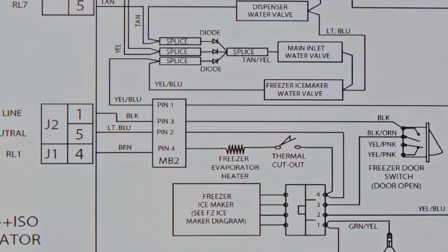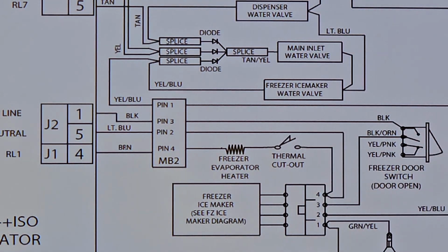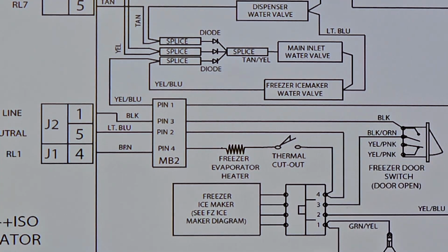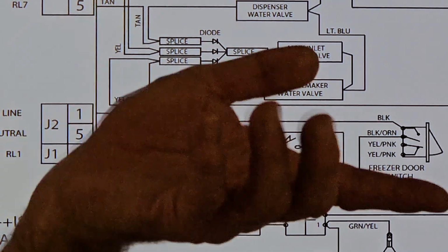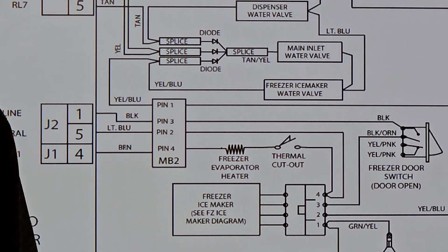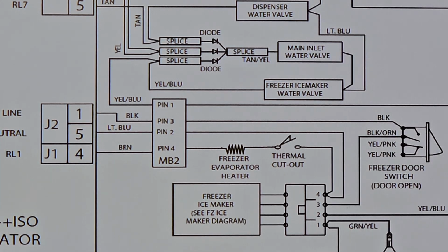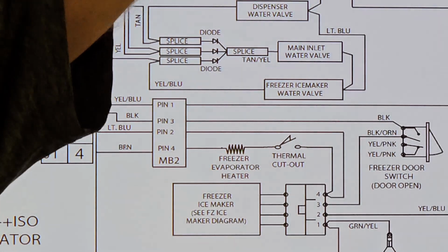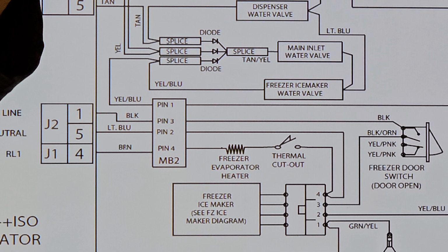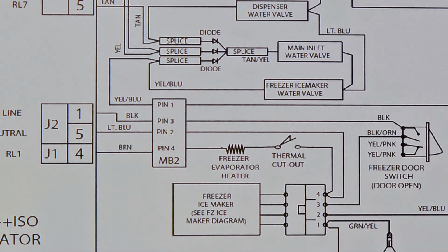So you see how a simple ice maker problem, we could have water flow, we could have an electrical problem, or it may not even be the ice maker, it may be a freon problem, it may be a defrost problem in that compartment that's not allowing it to get cold enough and do its job. But the refrigerator could still operate. It's just a little tiny evaporator up in the freezer compartment, and if it doesn't defrost, then we have a cold problem, we don't make ice.